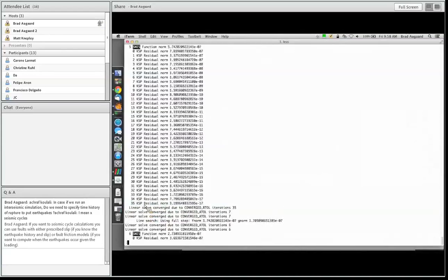And so you can look and sort of diagnose to make sure everything's converging. By looking at where my tolerances are, I can pick out that, oh, I'm still doing relative tolerance, I really should be doing absolute tolerance. And so I'll go in after we look at the results, and we can clean up our tolerances so we can have a better, faster convergence.